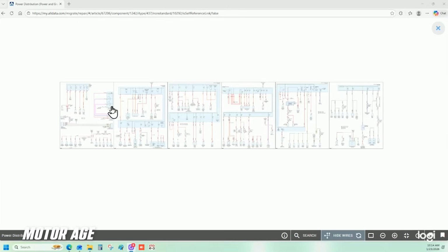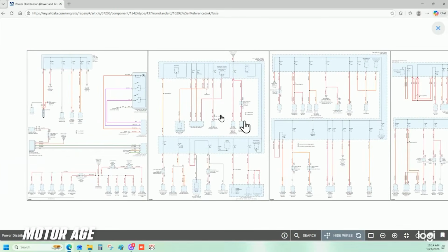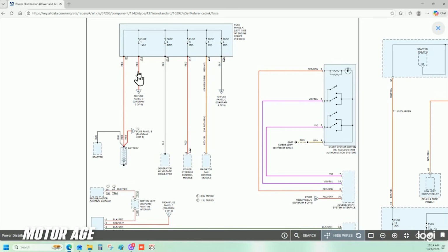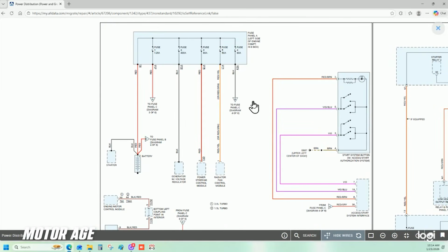What we can see here, and I will zoom in momentarily, is 5 specific screens simply demonstrating power distribution to this vehicle. Meaning everything you see on this screen right here has a potential to create a parasitic drain and discharge the battery, deplete it of its stored electrons, leaving the vehicle dead when the customer approaches it. But if we take the time to analyze our diagram, we'll realize that our battery source right here has only a few pathways for current flow, main pathways for current flow to travel throughout the rest of this vehicle's electrical infrastructure.